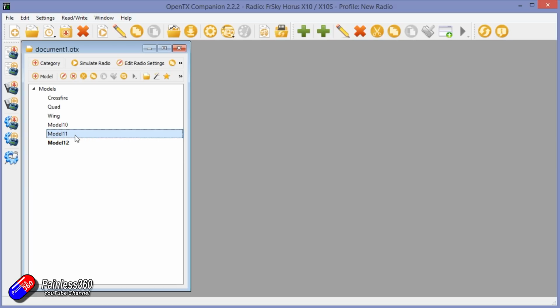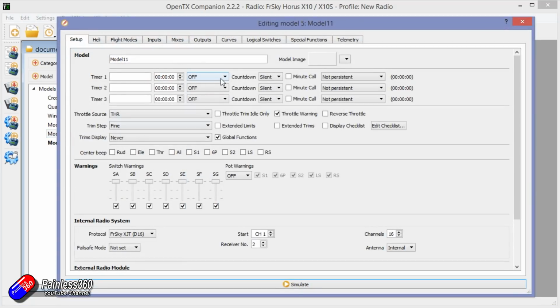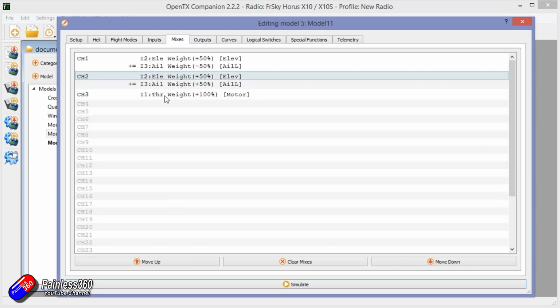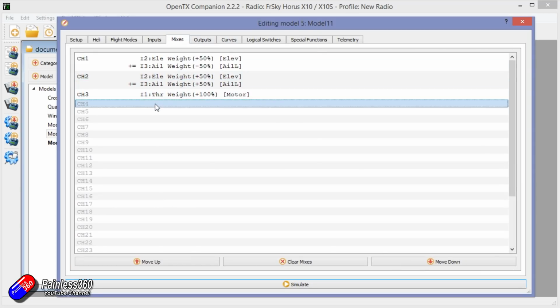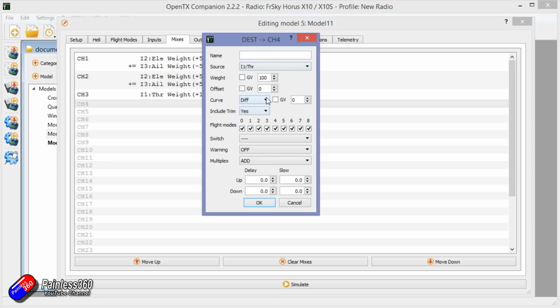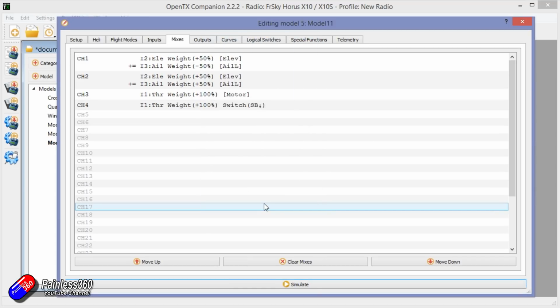The second thing is, be careful when you're setting this up. Playing with this, and I've had reports that some of the switch positions in some of the modes are slightly different. So for example, when you're setting up maybe mixes, you're setting up individual controls. So say we're going to add a control here, we'll put on a particular switch position. Some of these switches may or may not be the right way round, so you might have to just triple check when you write it all back onto the radio that it's actually all going to work okay.